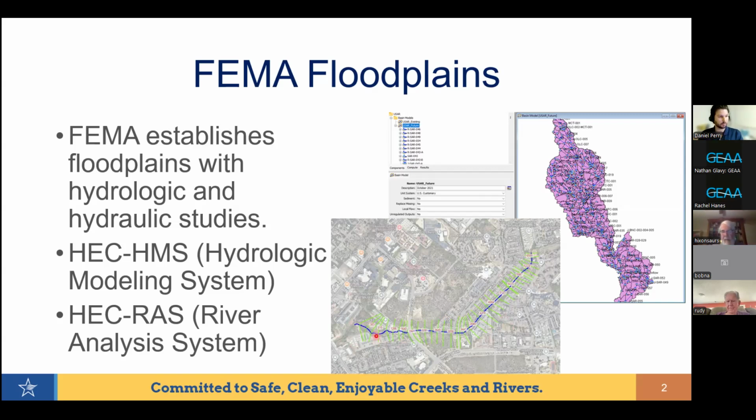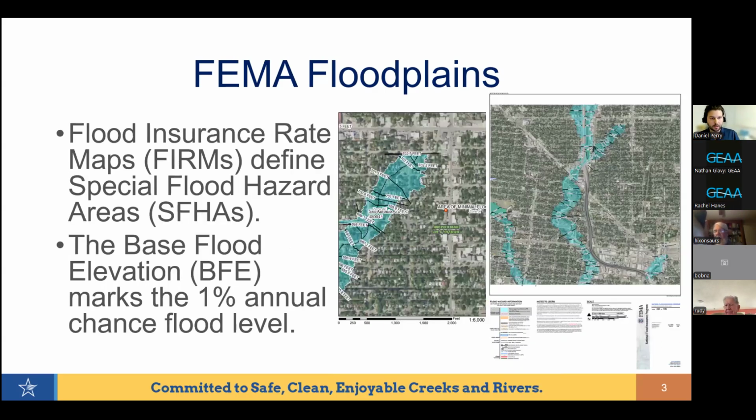So this model is doing a 1D calculation from upstream to downstream, and what these cross sections are seeing is the terrain that we're applying to each individual cross section. They aren't seeing the terrain in between them. They're interpolating from cross section to cross section, and we're trying to place them at very obvious areas of terrain changes.